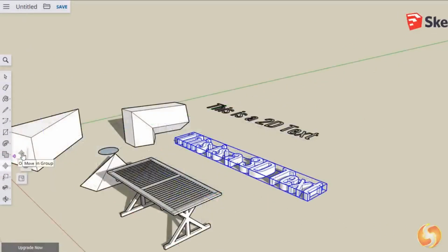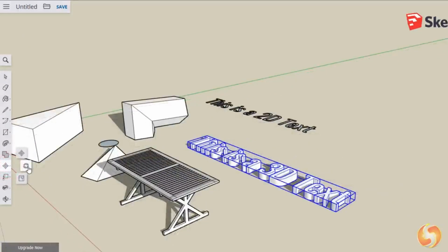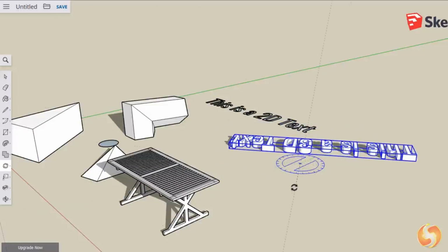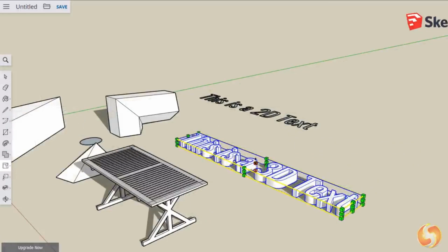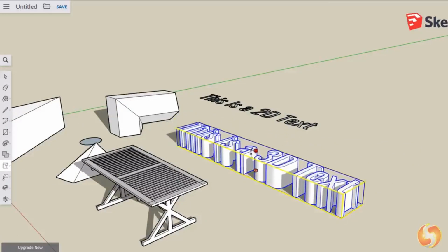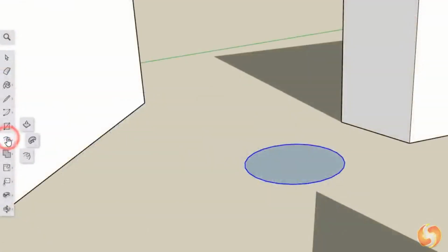Use the Move tool to move selected objects where you like. Whereas choose the Rotate tool to rotate these by fixing the main anchor point and then the rotation angle. You will rotate on the ground plane when the goniometer is shown in blue color. Enable the Scale tool to scale the object by clicking and dragging couples of cubes toward different 2D and 3D directions. Whereas use the Offset tool to add a 2D contour, which keeps a fixed distance from the original object perimeter.